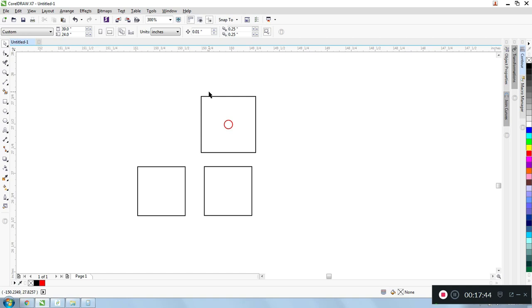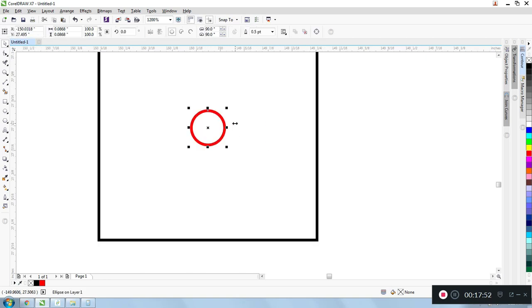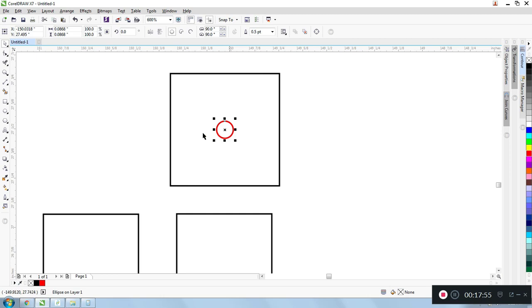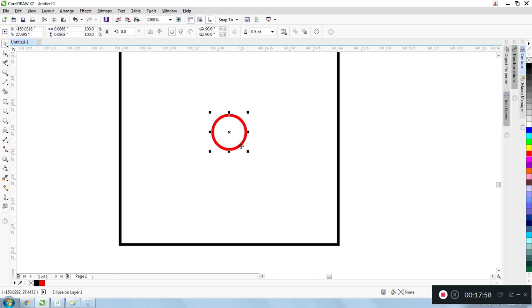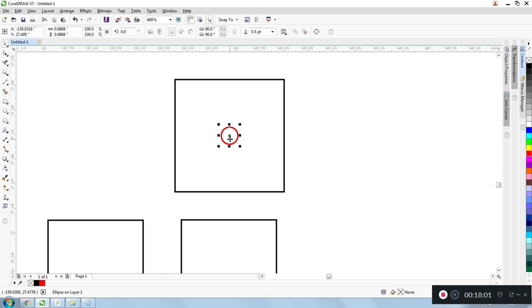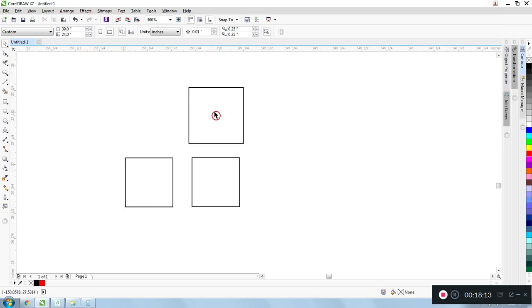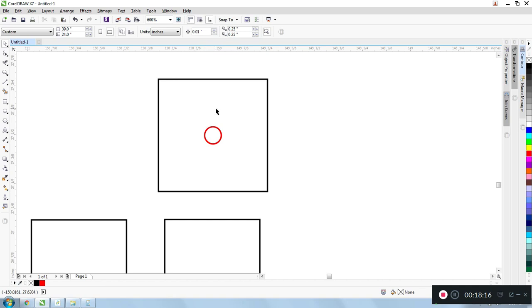That piece can pop up and pop out of there and revert back to its warpedness. So it's a really smart idea to cut the interior features first, because if this cuts the outer and it warps out of place, and you cut your red circle later, there's a strong possibility that your circle's going to be in the wrong place relative to your external cut line. So I always cut interior lines first, and for that reason I make my interior bolt holes, or, we cut out a million things, so whatever it is, just cut interior parts out first, or do your engraving first before you cut out the external shape.